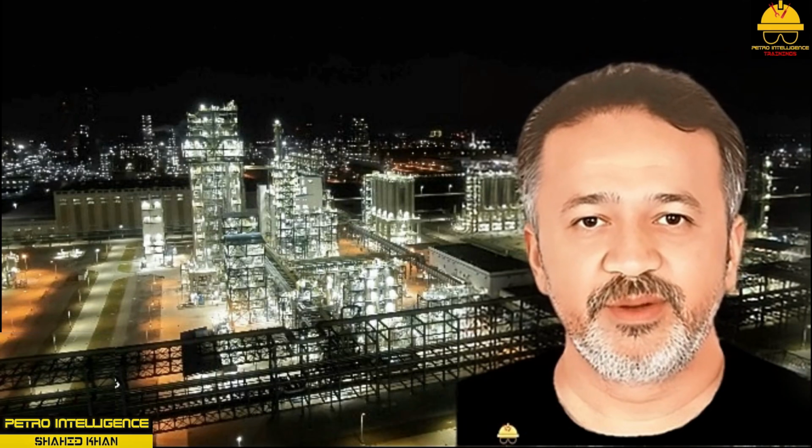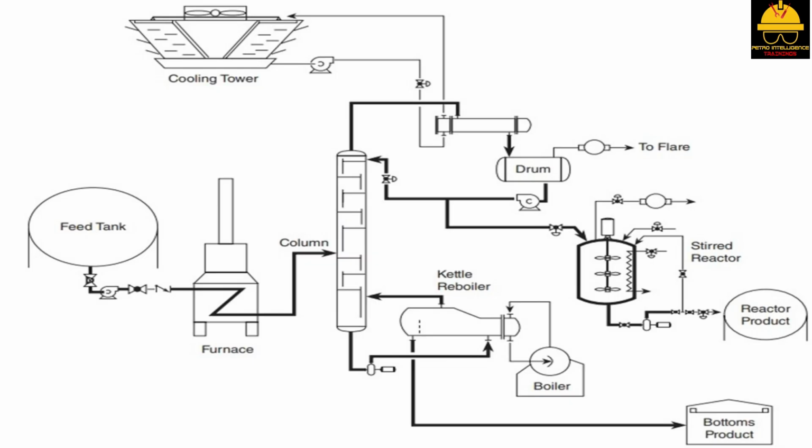This picture shows the basic relationships and flow paths found in a process unit. It is easier to understand a simple flow diagram if it is broken down into sections: feed, preheating, the process, and the final products. This simple left-to-right approach allows a technician to first identify where the process starts and where it will eventually end. The feed section includes the feed tanks, mixers, piping, and valves.